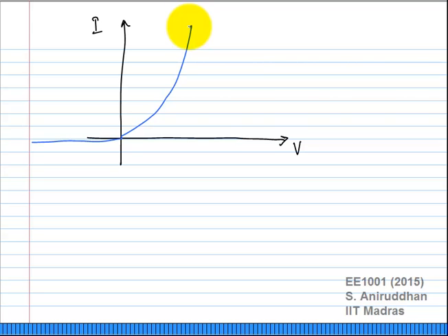We are easily able to do it when you have one diode: one resistor, one diode, one voltage source. You can iterate and solve it. If I give you 3 loops with one diode in each, it's going to be extremely difficult to solve. So how do you propose we handle that? Let us take a step back. I said you can iterate to find the solution. How do you know where to start the iteration? Will you start at 0, 0 or something? Or will you apply some random voltage? Or what would you do?